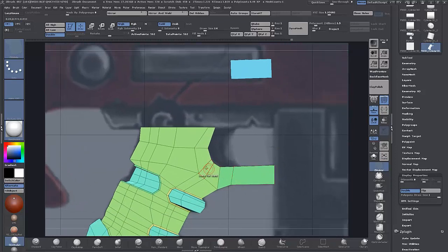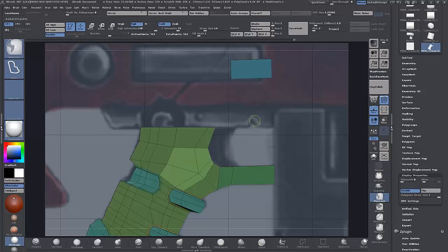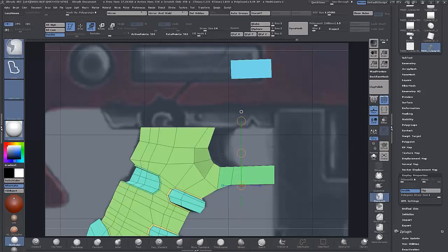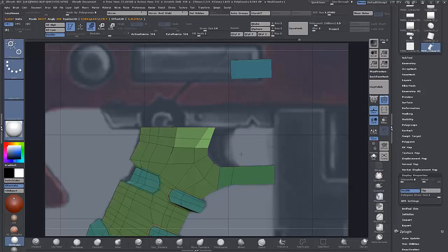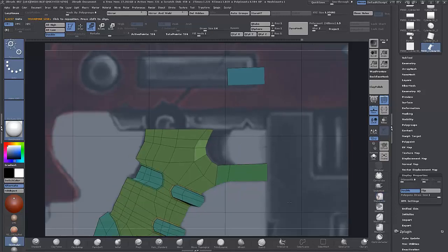the edge loop. You can see here, maybe you want to space some of these out a bit better. So just grab this, invert it, and just move it up slightly. Grab this, invert, and then we'll insert the loop here, and do the same. Grab the two of them. So whenever you add geometry in, you want to just make sure to kind of tweak it a bit there to maintain any sort of curvature that they already existed. So we'll just move and invert, and bring that in a bit more, and maybe this one as well, invert, and that should do us.